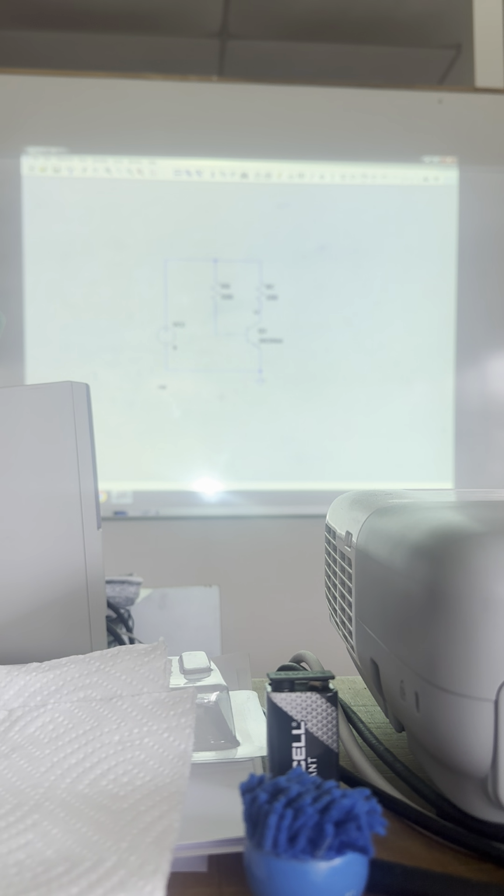There you go. Now we got 46 divided by 0.16. That's because beta is much higher. You with me so far? 287, 280, yeah, pretty close. Is everybody on board now? Now understand you can actually predict these things and control them. And definitely VC dropped to 4.3 volts, which was about what we got. Now, that's the beginning, part one.